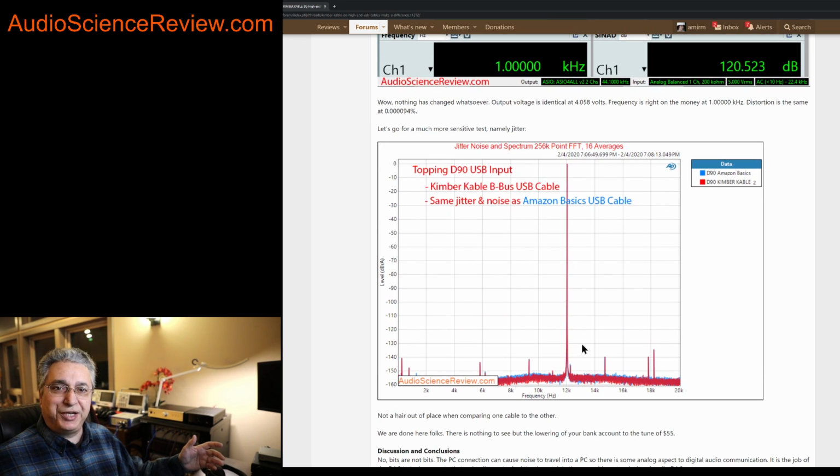A bugaboo is jitter. People think, oh, there's noise over USB. That noise goes into a DAC and creates jitter. Noise can cause jitter, so don't say that can't happen. If you don't clean up that 5 volt and you take it and feed it as a reference to a DAC, it can actually cause modulation of the output, and it will create symmetrical tones that you'll see around the main tone. We actually do have some jitter in this product.